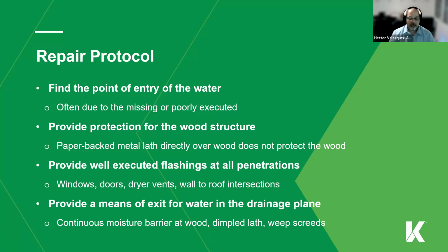Between the first floor and second floor, typically you will have another section with weep screed that you want water to come out. You don't want it to run from one floor to the other when you're having wood and CMU coming together.